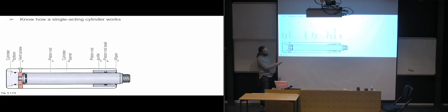We had the piston rod itself, the barrel of the cylinder on the outside here. We had the guide for the piston rod. Between the piston rod and the guide, there is just a very small diametrical clearance, so it's literally guiding the piston rod. By having this length over here with the very small clearance, the piston rod doesn't have room to move around while it's moving forwards. So it can only go in a straight line.